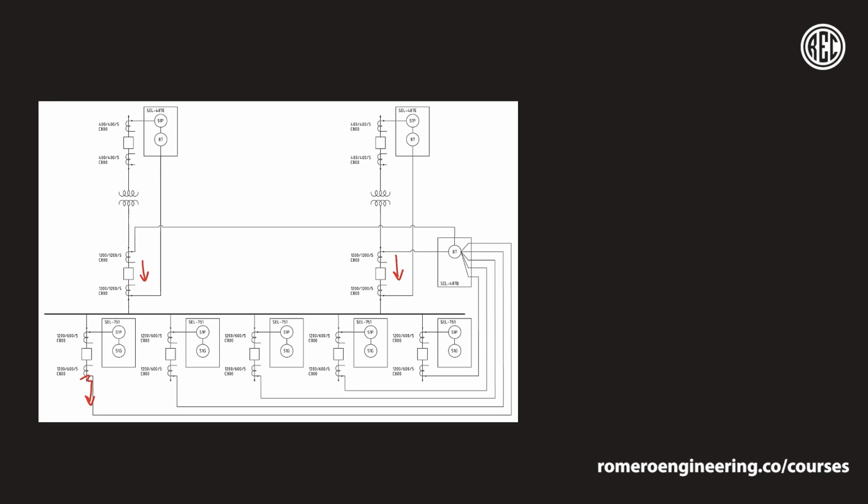All right, so first let's define two quantities for our bus differential protection scheme. Again, this is something that modern protective relays do. We're going to define what's called the operating current, which is also referred to as the differential current sometimes, and the restraining current. Let me actually write it over here. Again, these definitions vary per manufacturer or even per models of the same manufacturer.